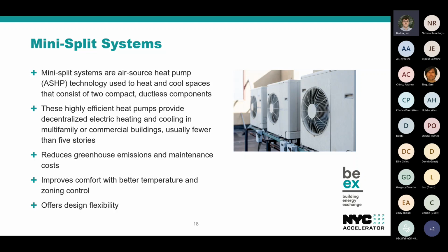These are very efficient pieces of equipment. An air source heat pump may produce 3 times as much heat energy output than input during operation. So these are highly efficient systems. They are commonly used to provide air conditioning by transferring heat from the air inside to the air outside. They can also function in reverse to provide heat. Typically, there's one outdoor unit connected to one indoor unit via refrigerant lines, and these require minimal exterior wall penetration, which reduces the porosity of the envelope and the loss of conditioned air through the building envelope.